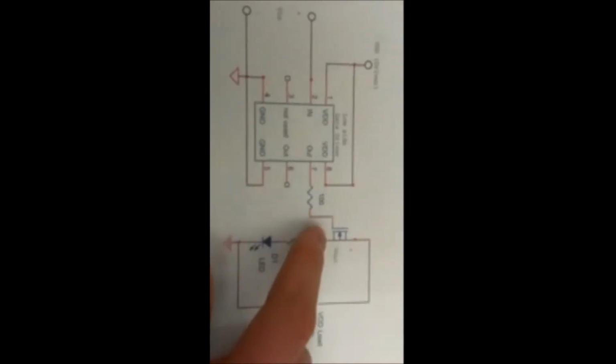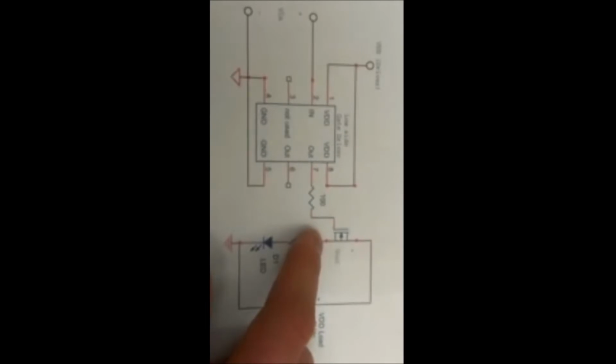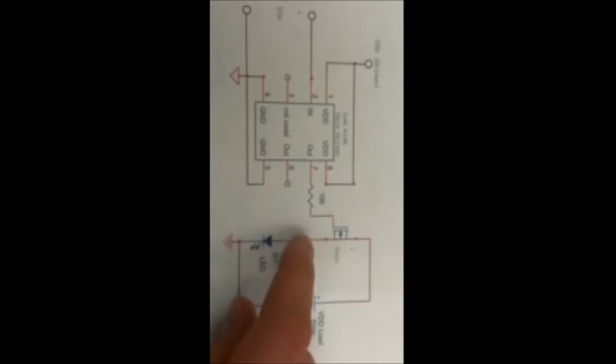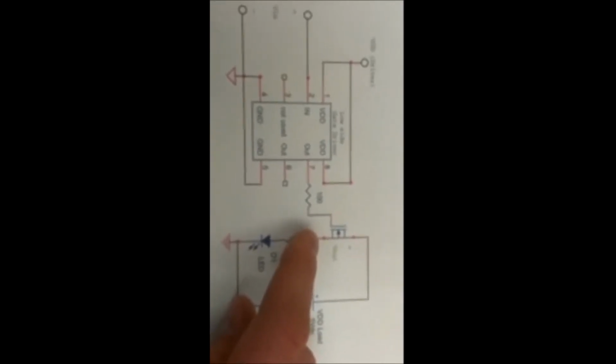If there wasn't a floating node power supply, VS would reverse bias the gate to source, and the MOSFET would turn off as soon as it turned on. However, because of the floating node, the gate voltage floats on top of the source voltage, keeping the MOSFET always in saturation. This is the low side gate driver with a high side switch in action. And the LED comes on for the win.